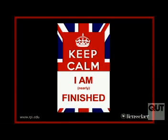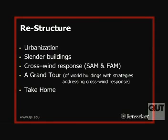So I'm nearly over. That should give us plenty of time for questions. I just want to recap. We've talked about urbanisation, and the need for taller, denser cities. And in the 15 years I've been away from Brisbane, that's certainly happened. You have a much taller, denser city, so you see it here in your own backyard. I've talked about slenderness of buildings, and that's because we're dealing with plot sizes that are relatively small in inner city spaces because of the cost. Talked about crosswind response, that's the sideways motion of the flow, and ways to control that, either through solidic aerodynamic modification or fluidic aerodynamic modification. And then I've given you some examples of that.